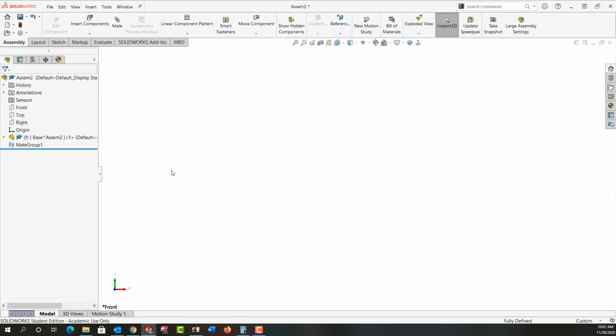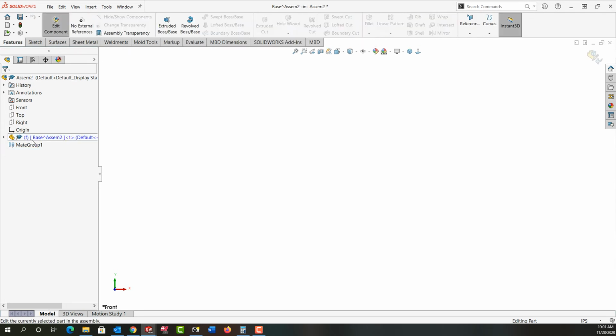So now that I've renamed the part, I want to actually start sketching and creating the part. So I'm going to select the part in the feature tree, and I'm going to come up here and say I want to edit the part. And the first thing I want to do is expand this. Notice how all this goes blue, and any other components in the assembly will be grayed out here in the feature tree and will be see-through in the graphics area, so I can focus on just this part.